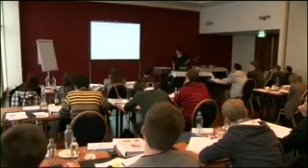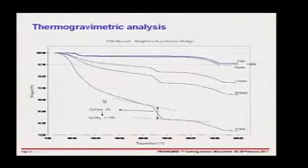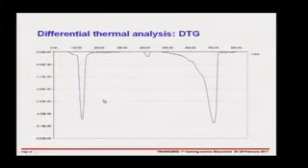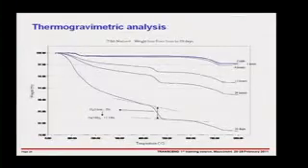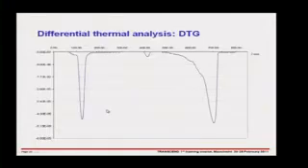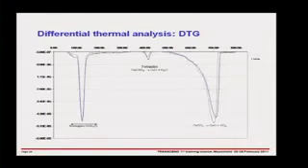So we've got a lot of other information here about our calcium silicate hydrate, etc., which is much better understood by looking at a differential version of this data. So that's thermogravimetric, that's your weight loss here, and then if we differentiate this curve, we get this kind of projection. That was our absorbed water at 2 minutes. This is our calcite peak from the fine limestone. You see, that's designated as ettringite. It might be a bit of ettringite as well.